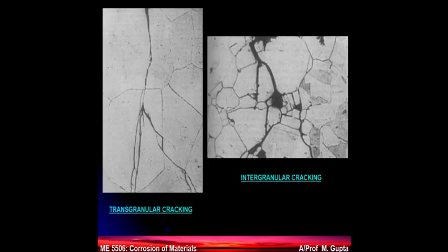To be very clear about the concept of intergranular, there's another word which material scientists use, which is transgranular. It's good to understand the difference between them. Inter means along the grain boundary. For example, this is grain number 1 here, and you see that the damage is going along the grain boundaries of different grains, and that's how the material failed. But when we use the word transgranular, that means the damage goes through the grain, not through the grain boundary.